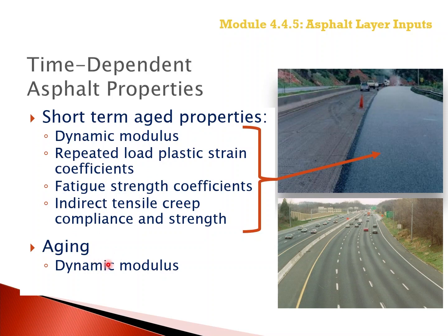The PMED software then only ages the dynamic modulus over the design life of the structure. And that aging is dependent on time or years, as well as depth within the flexible pavement structure or asphalt layers.